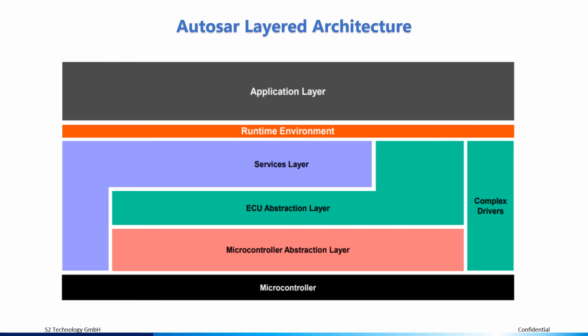So the AUTOSAR architecture is further divided into the AUTOSAR layered architecture, wherein BSW is further divided into the microcontroller abstraction layer, ECU abstraction layer, services layer, and the complex device drivers. What the microcontroller abstraction layer basically does is it speaks with the controllers. So it has all the drivers implemented in the microcontroller abstraction layer.